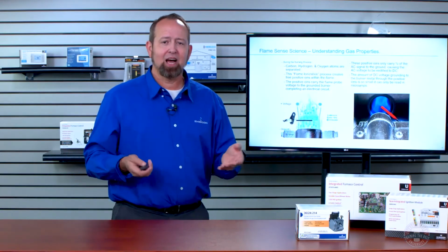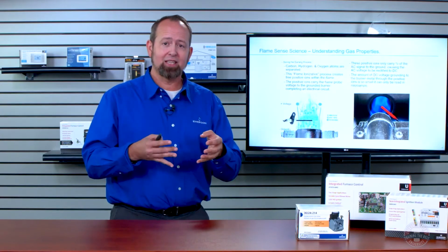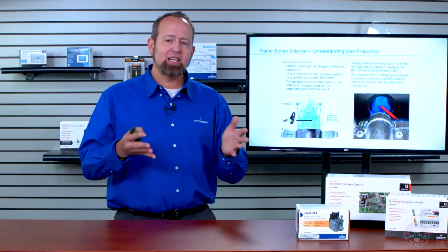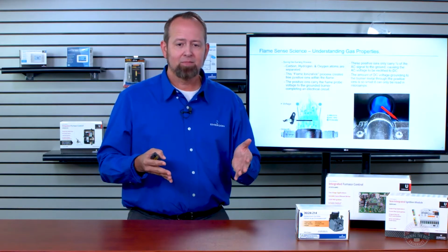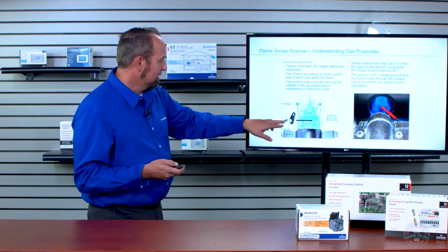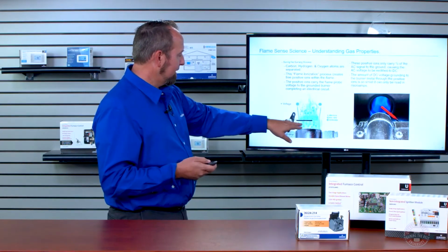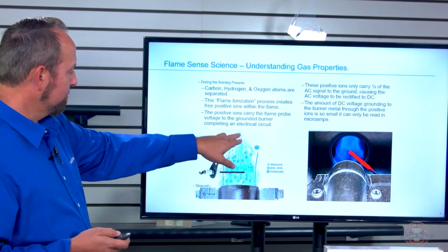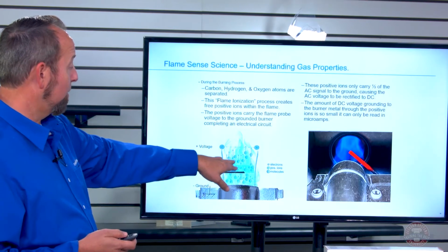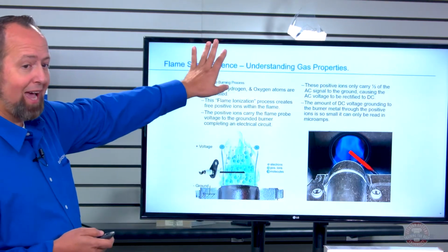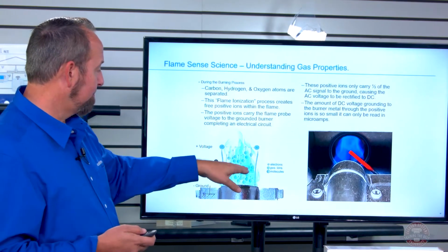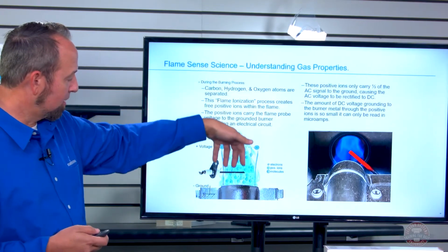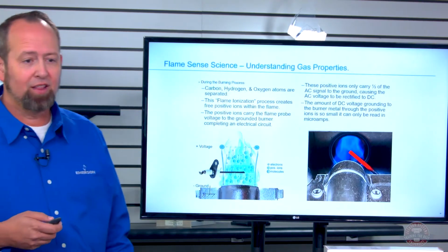During this ionization, where these atoms are burnt and they come together, the positive ions are freed from this process. My slide here shows that as we have burning, the negative molecules and the electrons, which are the negative particles, continue on through the gas, whereas the positive ions actually create what's called an ionic wind and are pulled back towards the burner.